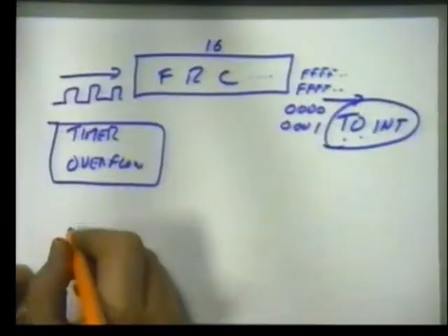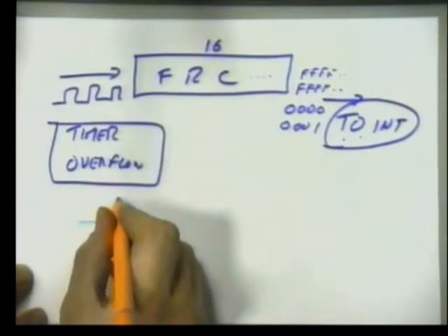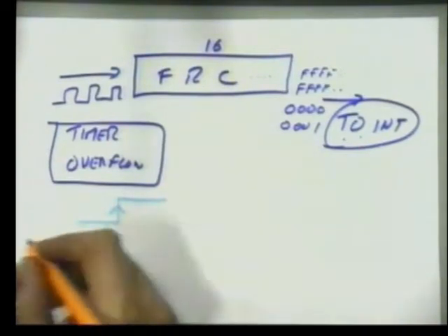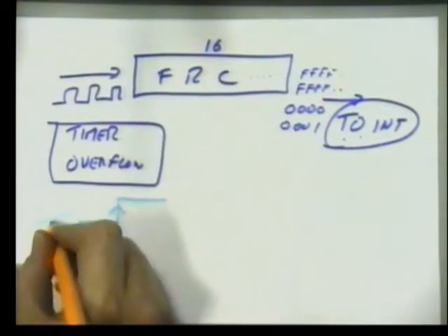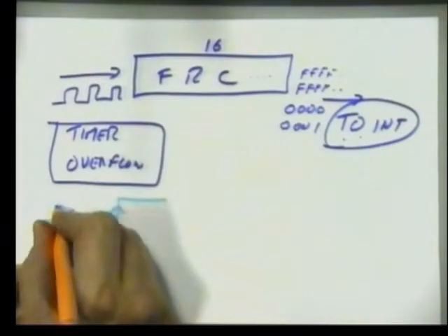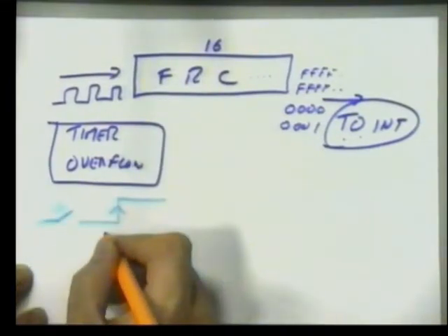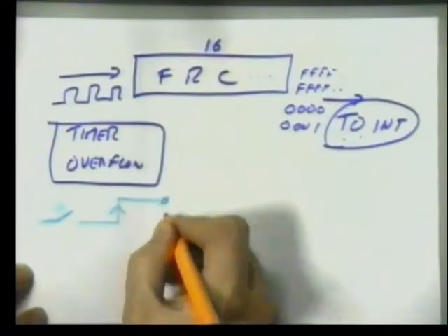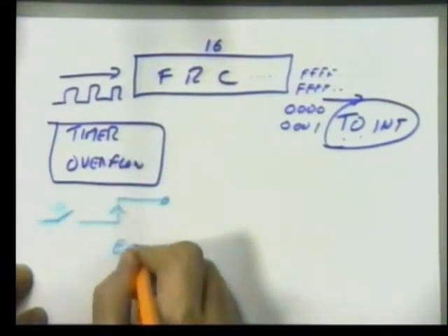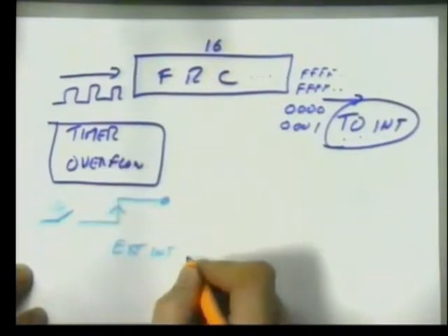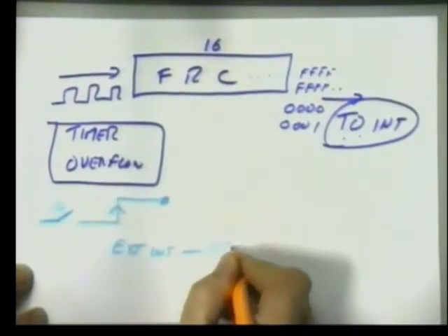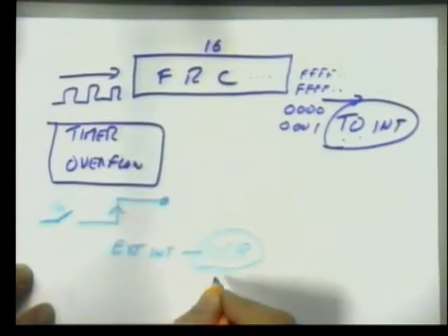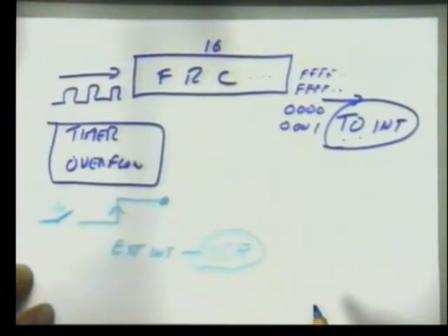So let's assume we have here a rising edge signal from some external device. Let's say this is our switch or our brake or our pedal or our timer. Something has given us this rising edge event. Now we could process this using an external interrupt, and that could signal an interrupt service routine to start operating that services that external event.